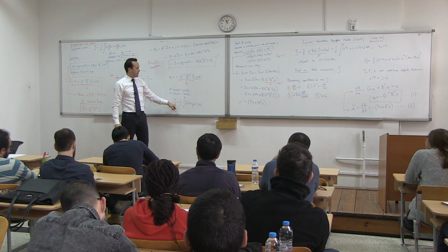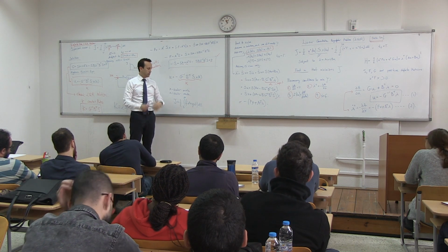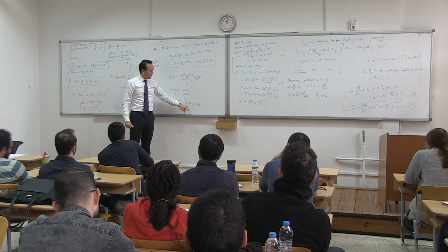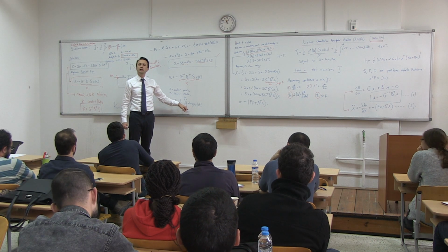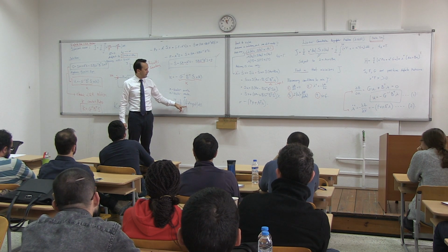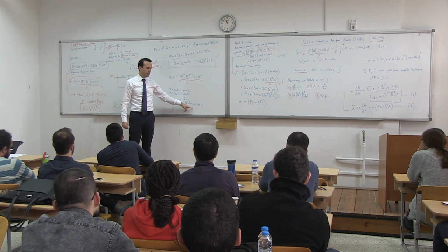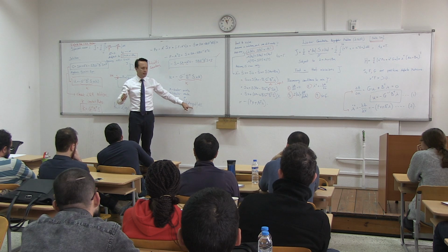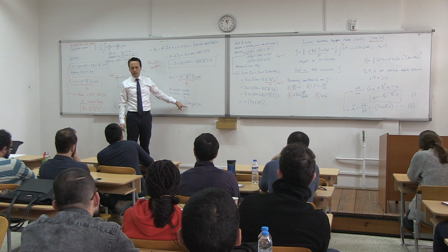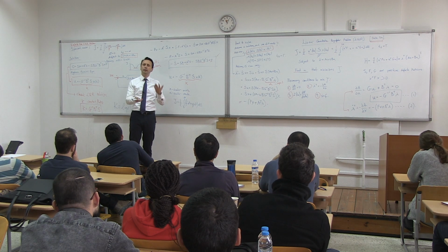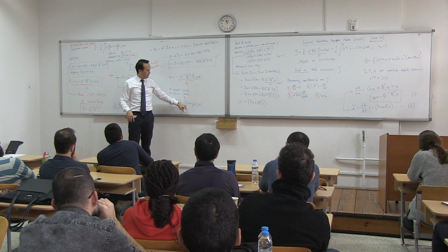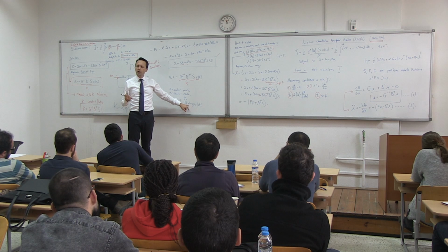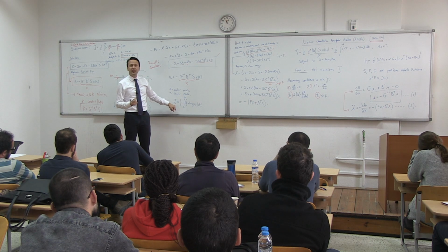So if I want to minimize J, then x and u have to become small, of course. But they are multiplied with numbers F and G. Now here's the question. Let's think of F as a large number, and G is a small number. And when I say small and large, let's make G 0.1 and F 1000. Okay? And let's say x and u are comparable numbers. Okay, they are all degrees, let's say. So if F is a very large number, a small change in x would have a big effect in J, right?